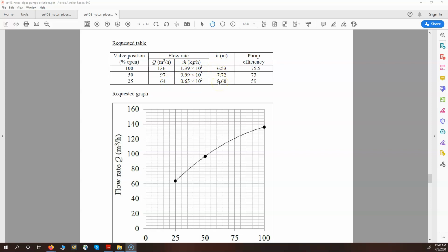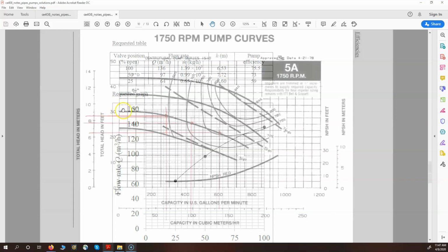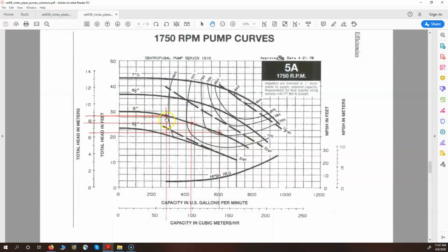Now, about the pump efficiency, how do we get that? Well, here's the pump characteristic for that 6-inch impeller we're supposed to be using, and for the three flow rates that I got from those intersections of the pump characteristic with the three system curves, the three operating positions were this flow rate, and this flow rate. Flow rates are going down because I was choking off the flow more and more. And then just by eyeballing this graph, you can see what the efficiencies are.